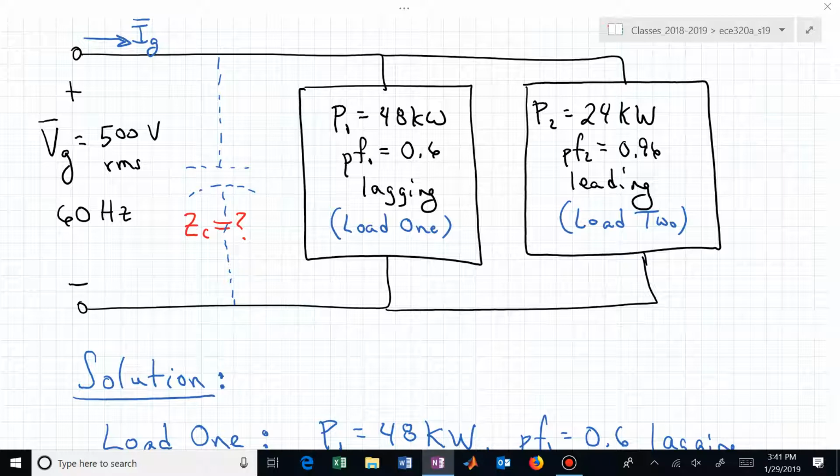So when you see a power factor of 0.6, you go, oh, relative to 45 degrees, what's the angle? If we had an angle of 45 degrees, how are the real part component and the reactive component compared in size? They're equal. So now we know, if we're doing the math, and we see a power factor of 0.6, whoa, that means that our angle might be bigger than 45. We'll work through that in just a minute.